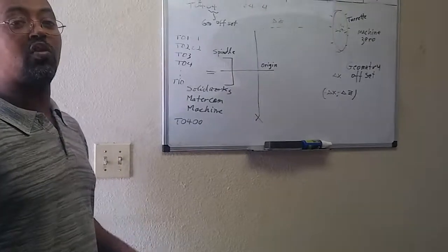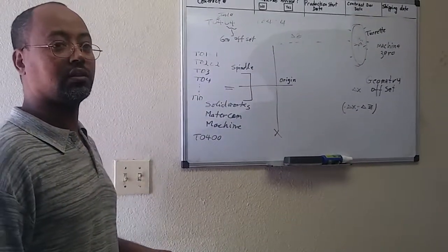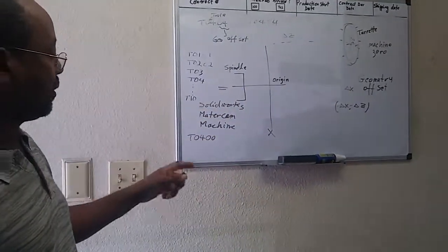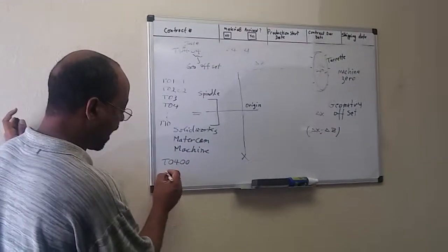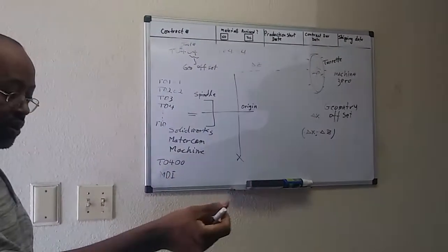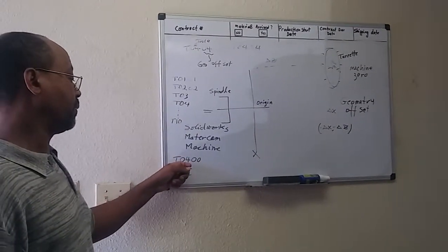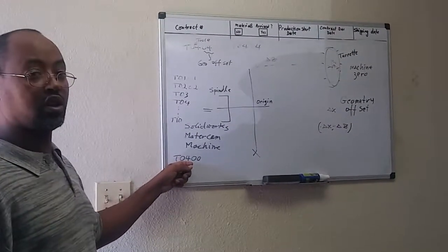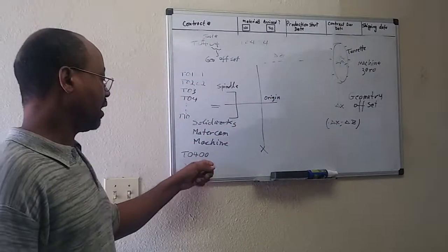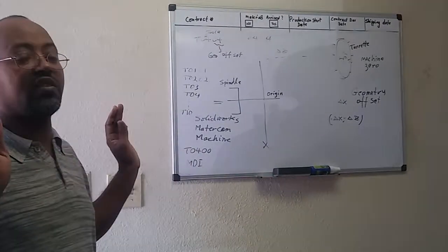It means tool number 4 without geometry set values. So when you establish the offset geometry, you go to the MDI mode. You switch to the MDI mode, and then you enter 20400. That's what we're going to do hands-on today. And then you say, select that tool. It will bring that tool with any offset geometry.